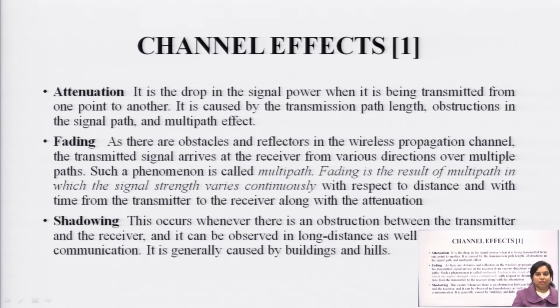There are 2 different types of modeling, indoor channel modeling and outdoor channel modeling. In case of indoor, we do not have to consider any obstacles like hilly areas, trees and all. In case of outdoor, we have to consider all these conditions. We have to see what will be the height of the transmitter, what will be the height of the receiver, and what is the distance between the transmitter and receiver. Because in case of outdoor, there is a high chance of non line of sight, and different obstacles are going to affect the quality of the signal. So, that is known as the outdoor channel modeling.